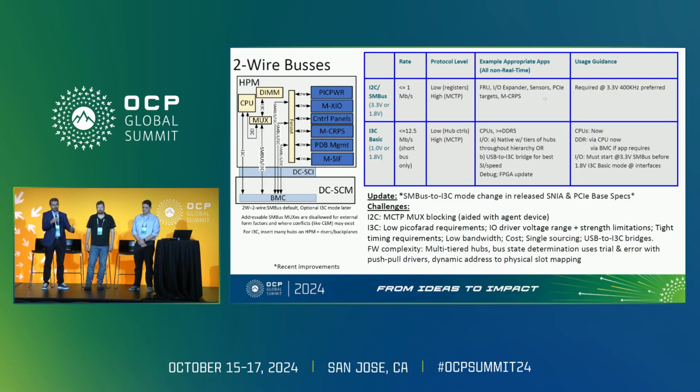So looking at all of that, the new solutions that come into the picture are solutions like I3C to USB bridges, where you can treat the I3C interface or I2C interface as the last inch interface on your system.